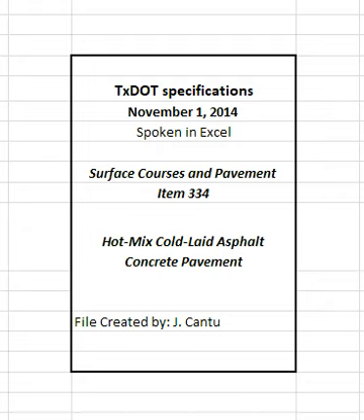2.2 Mineral filler. Mineral filler consists of finely divided mineral matter such as agricultural lime, crusher fines, hydrated lime, or fly ash. Mineral filler is allowed unless otherwise shown on the plans. Use no more than 2% hydrated lime or fly ash unless otherwise shown on the plans. The plans may require or disallow specific mineral fillers.